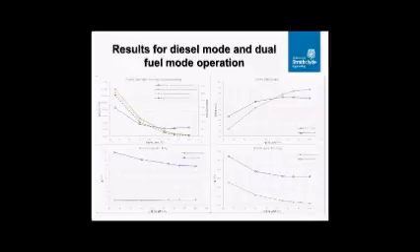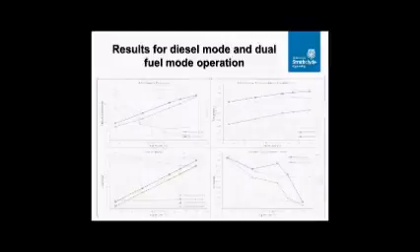In the present study, a marine four-stroke dual-fuel engine was investigated by using GT-Power software, which uses one-dimensional modeling. The main findings of the conducted research are that the engine in the dual-fuel mode operates with an almost constant air-to-fuel equivalence ratio, around 2.2, whereas much higher values of the air-fuel equivalence ratio are used for the diesel mode, corresponding to greater airflow.